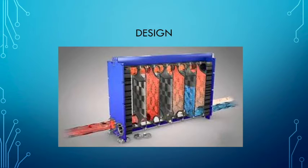Next, we go to the design. Okay, the design of a plate heat exchanger comprises several heat transfer plates held by a fixed plate and a loose pressure plate to form a complete unit. Each heat transfer plate has a gasket arrangement providing two separate channel systems.